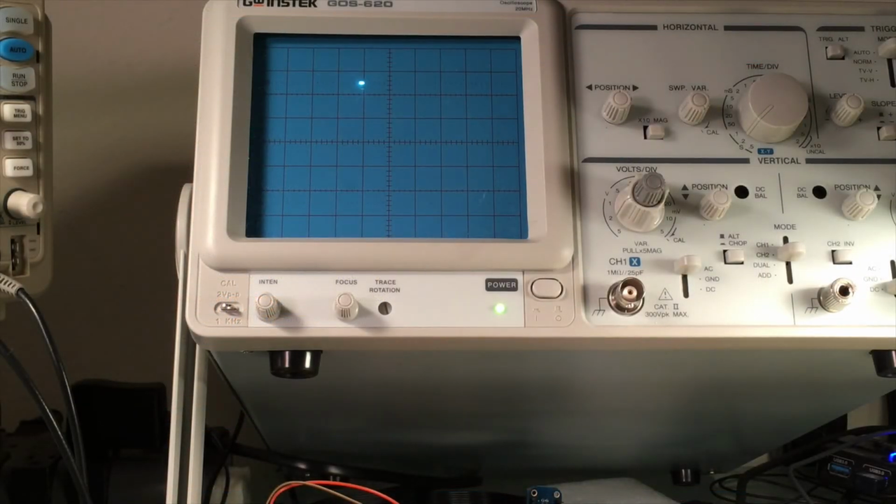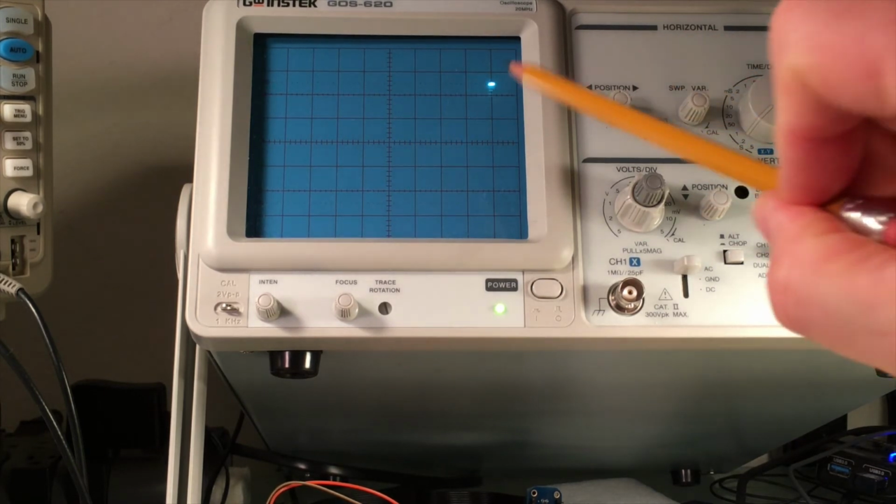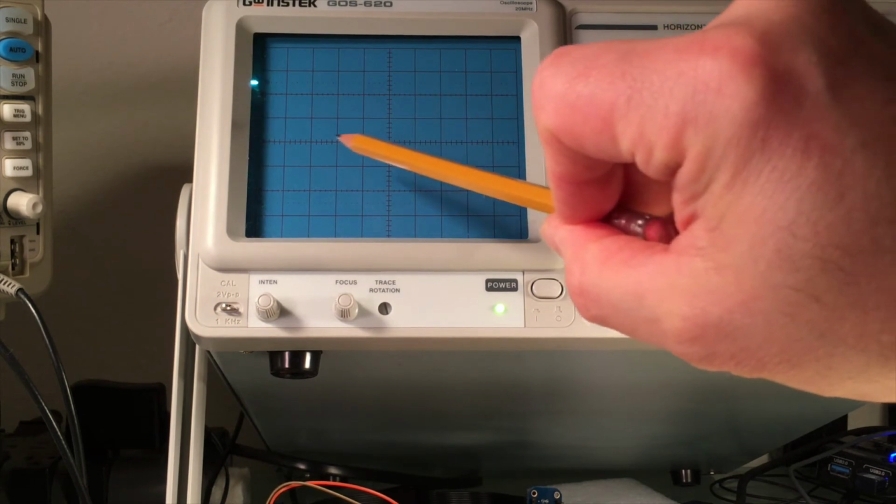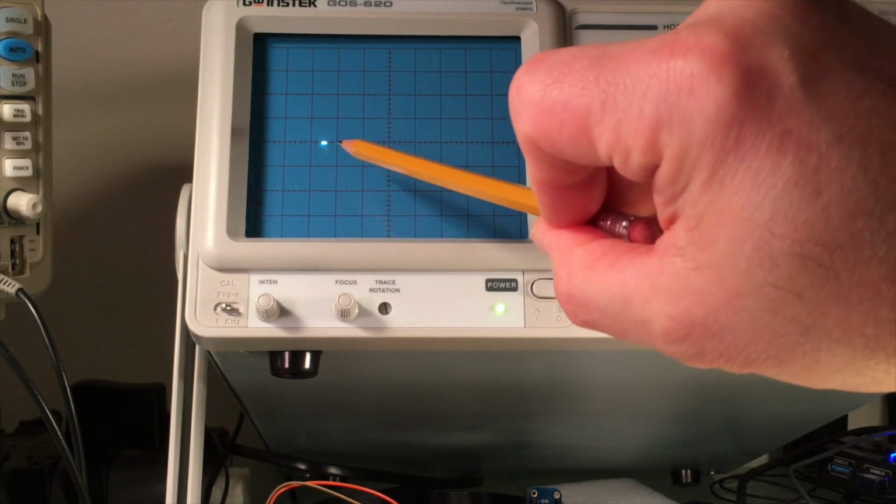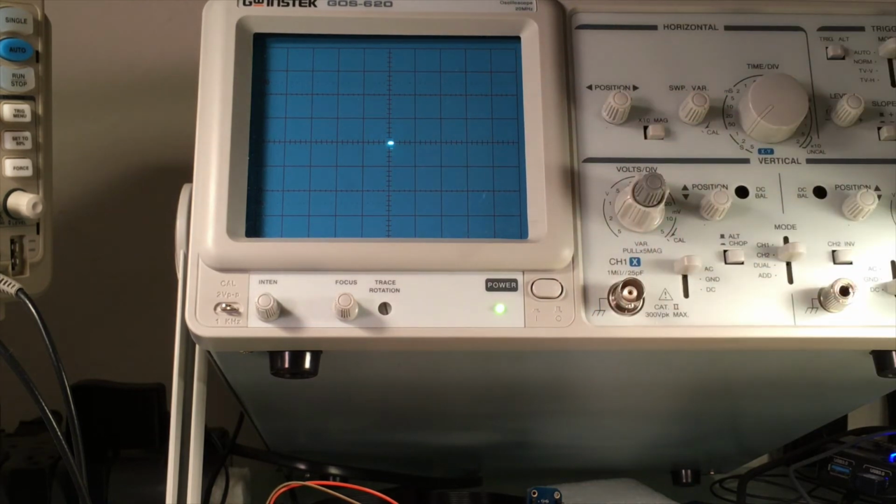Okay, so I've loaded the sketch into the Arduino, and this is the 1 hertz square wave being output. It looks kind of odd on the oscilloscope because it's such a low frequency. You usually don't measure or read things down at this level, but we can use the oscilloscope and just verify what we're seeing. So the time per division setting is set at 0.2 seconds. It's kind of hard to see how many divisions this is going across per cycle because it's going so slow, but I think it's like 5.